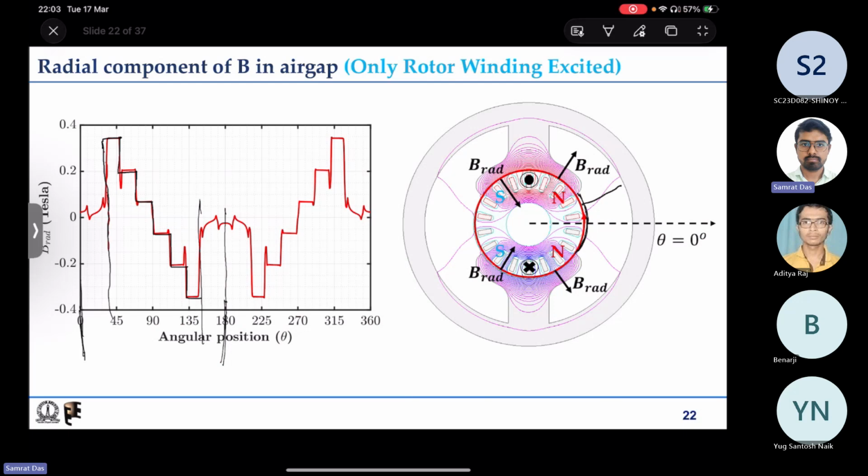where the length of flux line increases rapidly, like it's very big, it's approximately the height of the stator pole, it goes as high as that. For some sample values, the height can be a few millimeters to tens of millimeters, say 20 mm, maybe one dimension. But the G, where they were facing each other, may be only 0.5 mm.